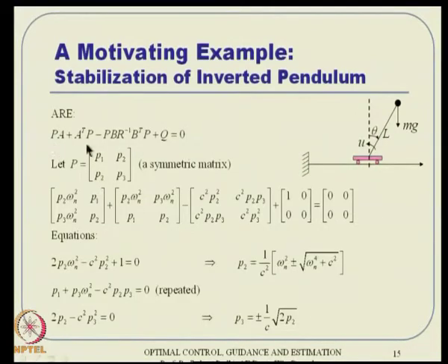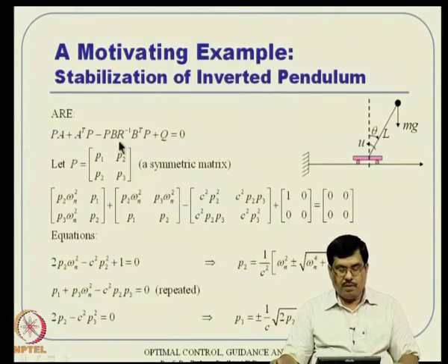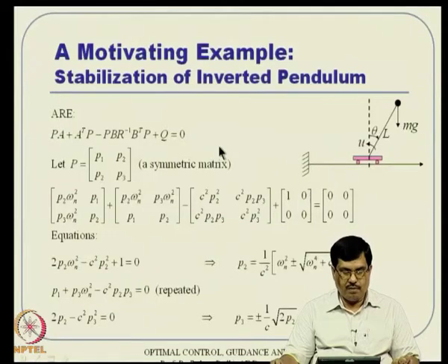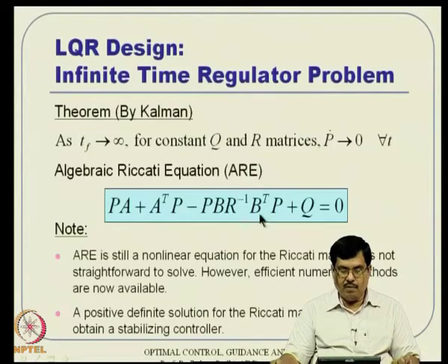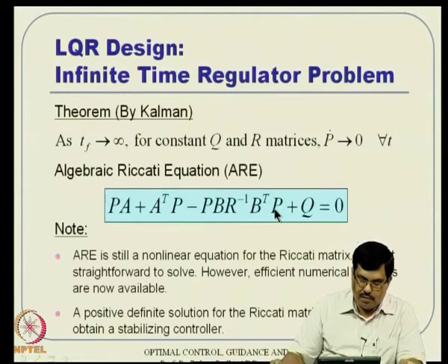So, we will put that, and this is one equation I will also recommend people taking this course should remember. Once you remember the Riccati equation, you are remembering two equations simultaneously. You are remembering the Riccati equation, but you are also remembering the Lyapunov equation. You take out this term and it is nothing but the Lyapunov equation, and these two equations appear very heavily in many of our fields. So, I thought it is good to remember this equation.